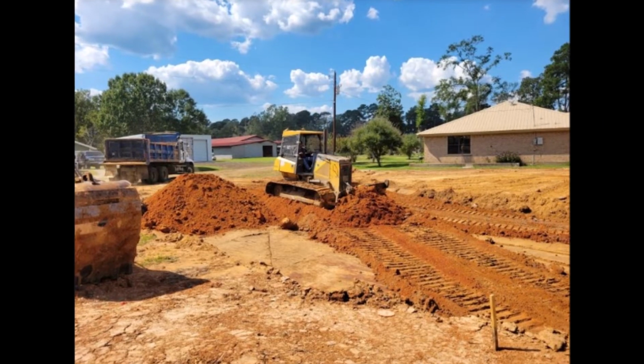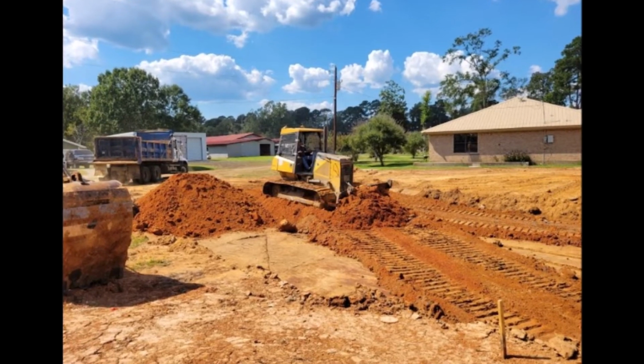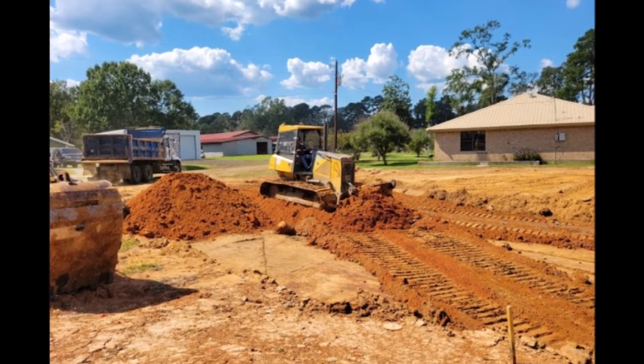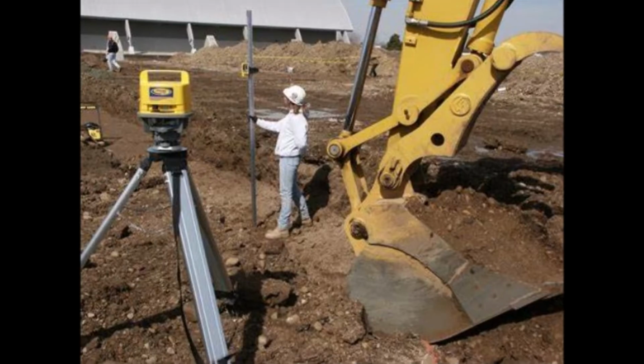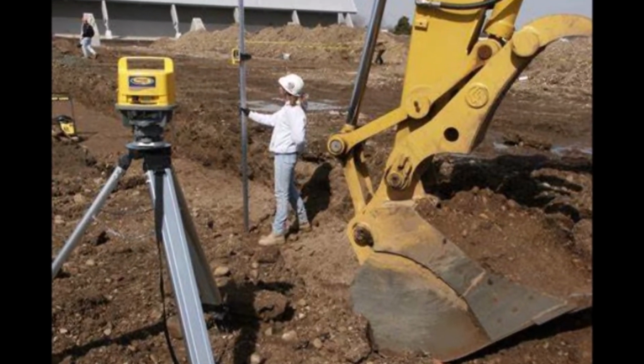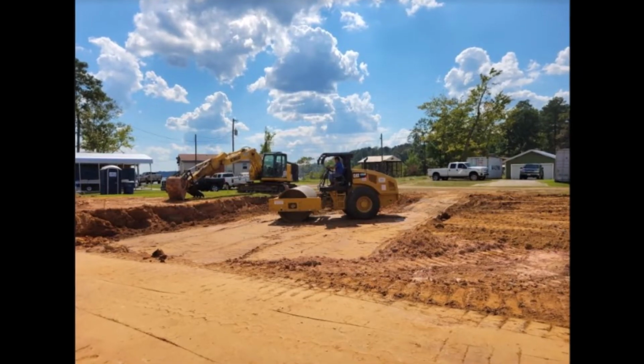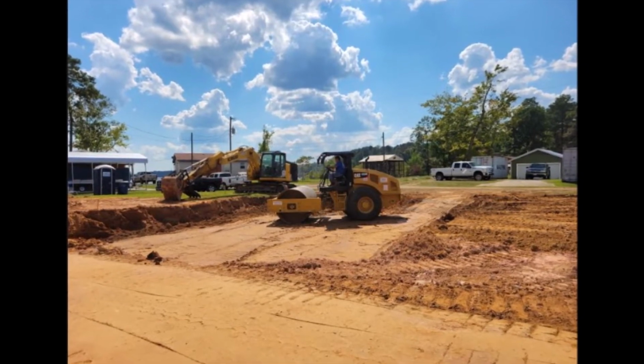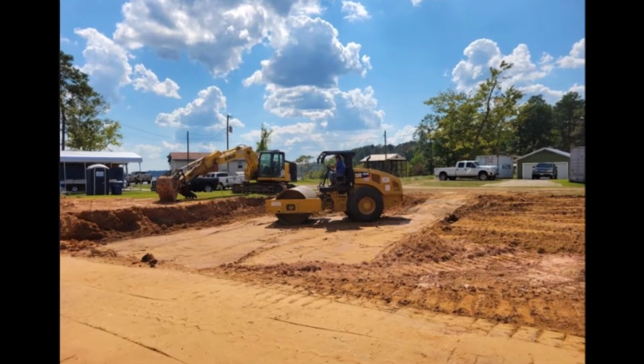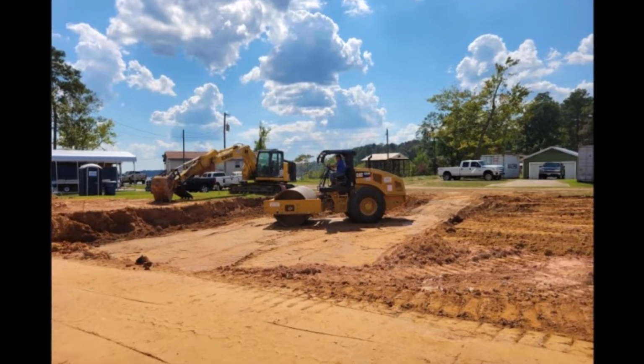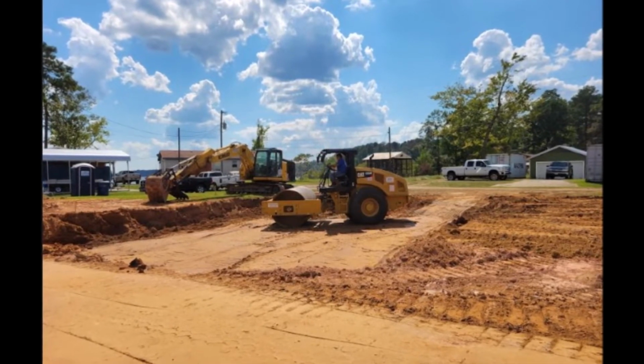You eliminate these deficiencies by inspecting the work during the placement of the foundation. You check the proper depth of excavation, the proper select fill material, and the placing of the fill material, and then inspecting the concrete foundation before and during the concrete pour.